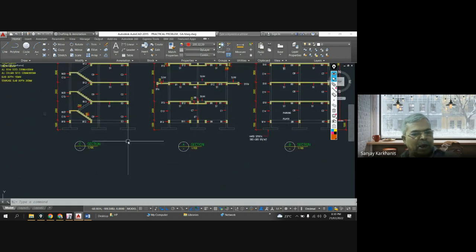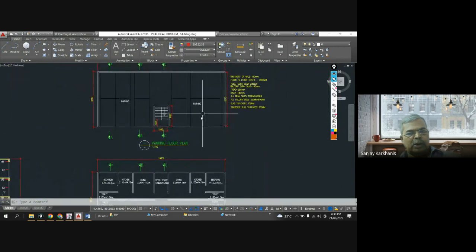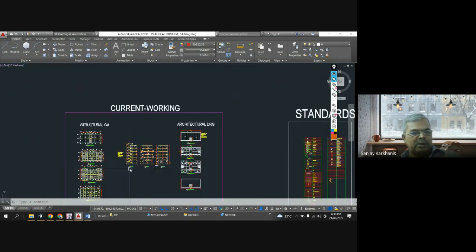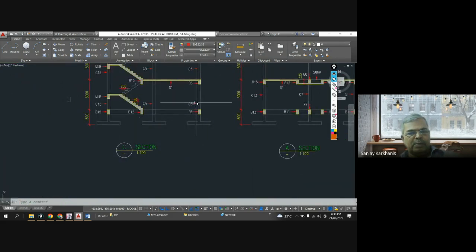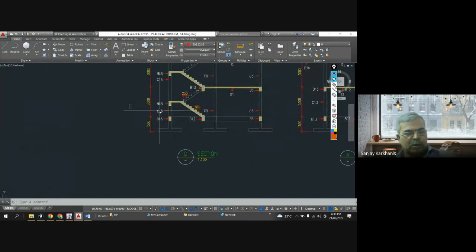So depending on that, whether you apply the loading on this or not is up to you. Sometimes you may say that there might be a wall of say 1 feet or maybe 2 feet. So you can apply that loading on the plain beams, and on this you will have to apply full wall load, and on this beam you have to apply 50% height of the wall, so 50% wall load.